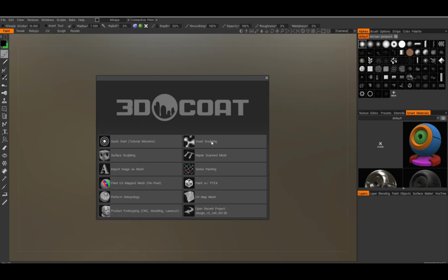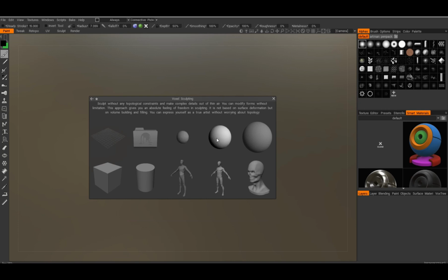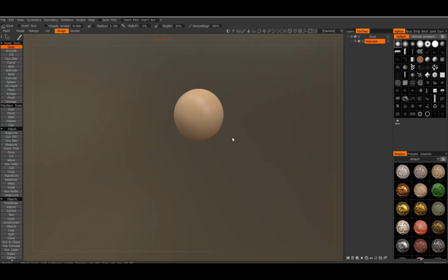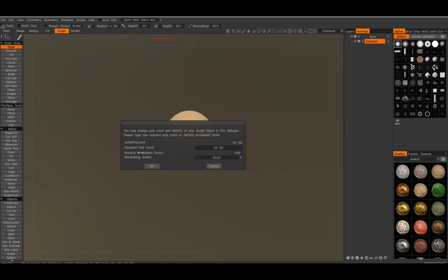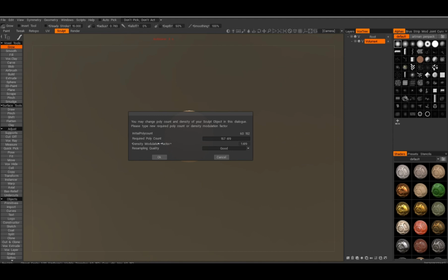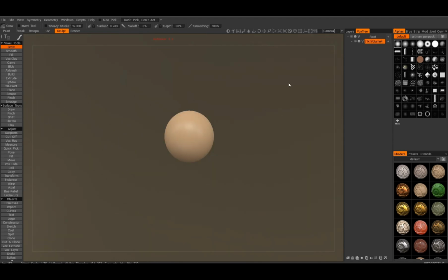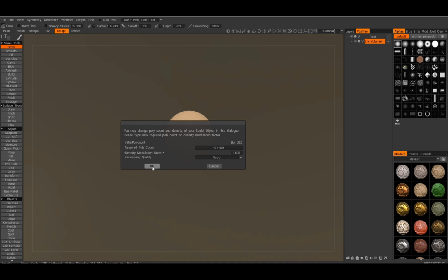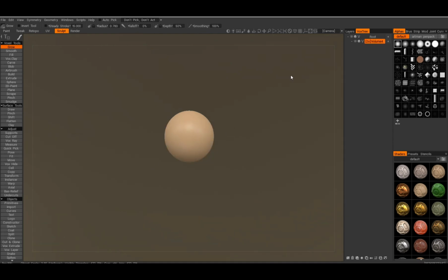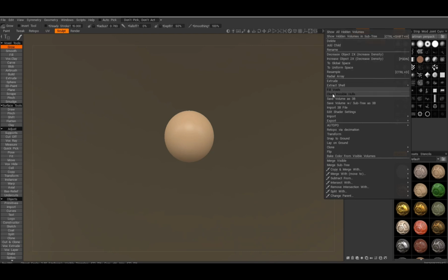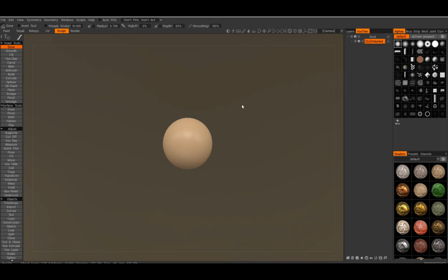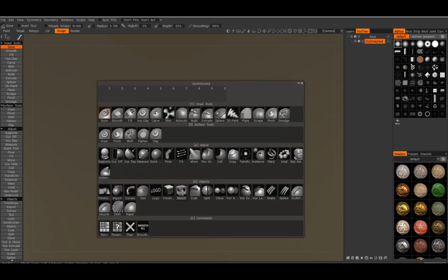Alright, so we start here with the voxel sculpting mode, and I start with the sphere. I will go up and increase the resolution of this resampled layer to like 200,000, even higher than that, because we need a fairly dense voxel layer here. Then I will clean this up. I have a hotkey to clean these layers, just backspace, and now we have an empty layer of voxels at proper resolution.